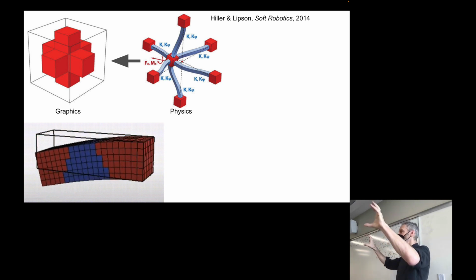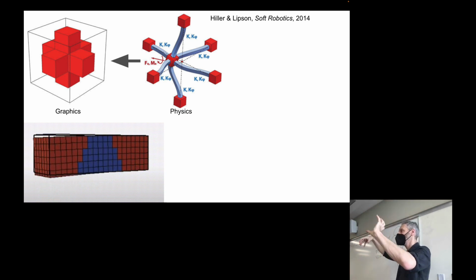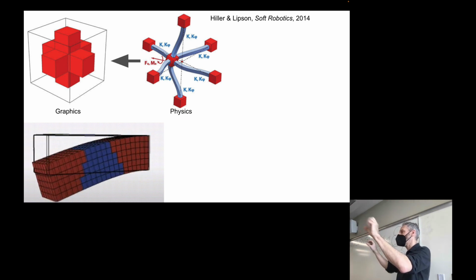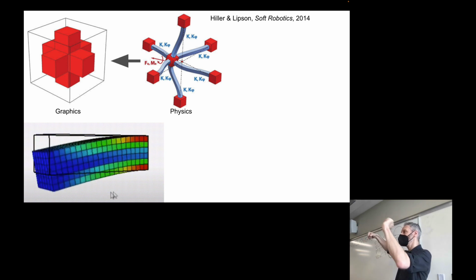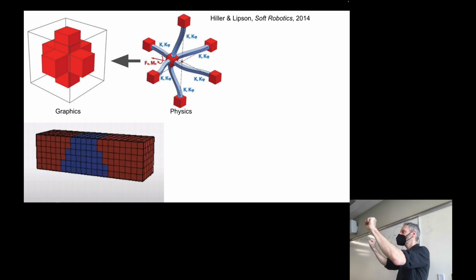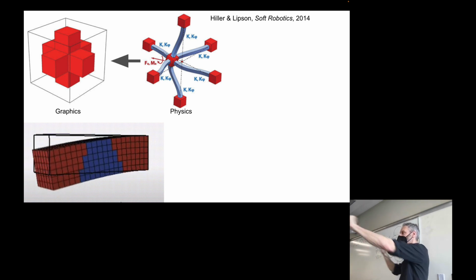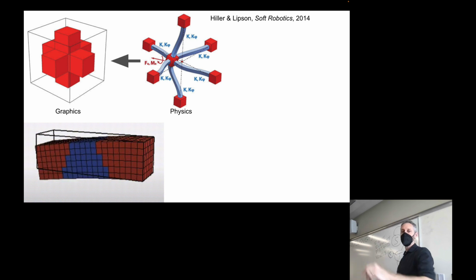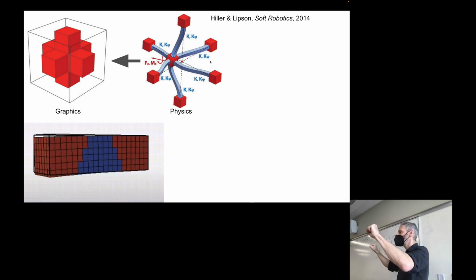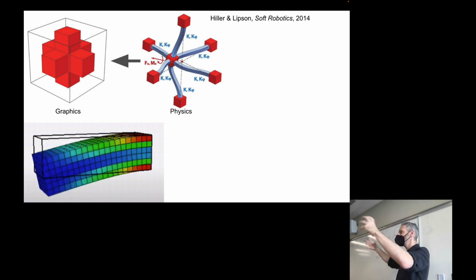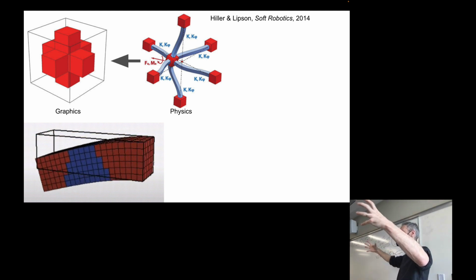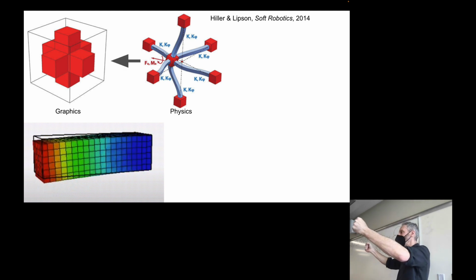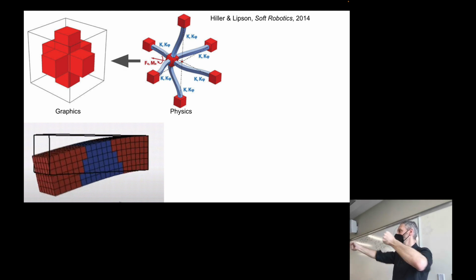Okay. Imagine we take a spring and instead of pulling or pushing, we also twist it. Those 2 numbers, stiffness and damping, don't really tell you how or whether the spring will resist torsion, twisting one end relative to the other, or shearing. We can take the 2 ends of a spring and I can push or pull the edge orthogonally to the direction of the spring, right? A beam is going to resist in a particular way, pulling and pushing. It's also going to resist torsion. So if you take a steel beam and you hold either end and you try and torque it, it's going to resist that just as much as it's going to resist pushing and pulling. And finally, a beam is also going to resist the attempt to try and shear it.